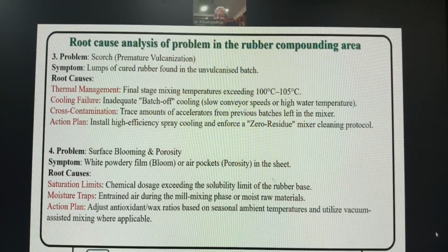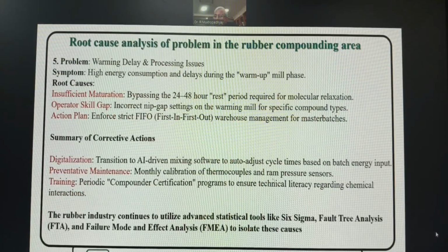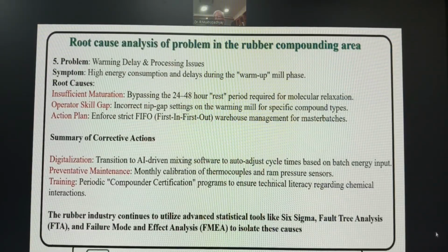A simple example: butyl rubber generally goes with paraffinic oil, maximum paraffinic oil. Paraffinic oil gives better compatibility, while others are poor. But in the case of natural rubber or SBR, naphthenic or low-PCA oil gives better results, and they don't ooze out, no problem. But if you go for a polar rubber, then an ester-type plasticizer or a high aromatic content plasticizer is needed.